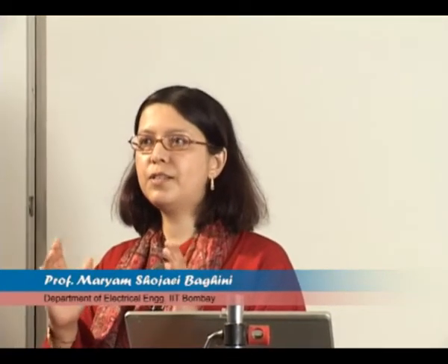I don't want to enter into the details, but what is important is that the specifications should be long lasting. They should not deviate from whatever we want. So that's why generating a bias for a circuit is very important. If the bias point of an analog circuit changes, you know that all specifications will change. So that's why stability and tolerance of bias to different sources of noise and different sorts of variation is an important issue.